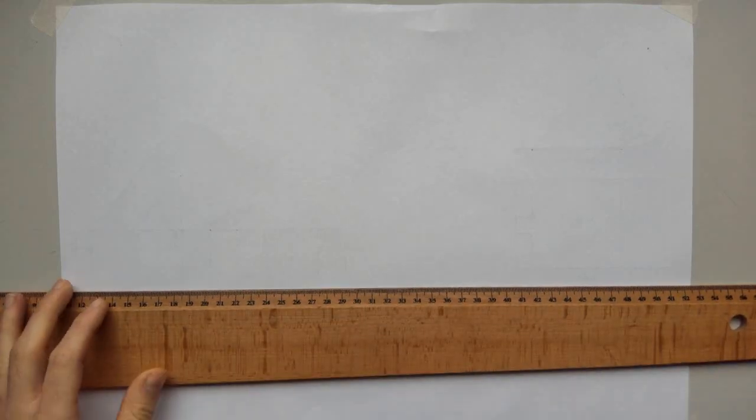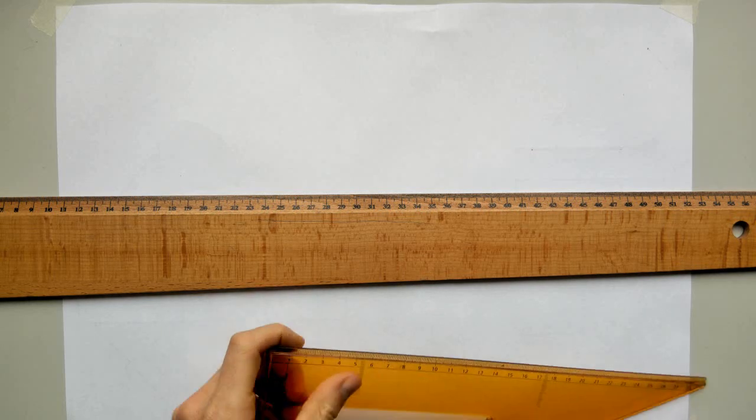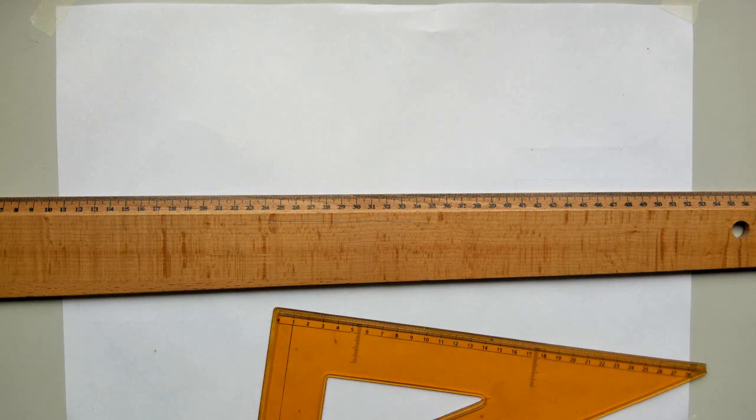So to start this question, I'm going to draw out my elevation and my end view. With the parabola given, I'm told the scale is 1 to 100, so I need to divide out all my measurements. For example, the first one is telling me that the height of the parabola is 7.5 meters, so 7,500 millimeters, divided by 100.